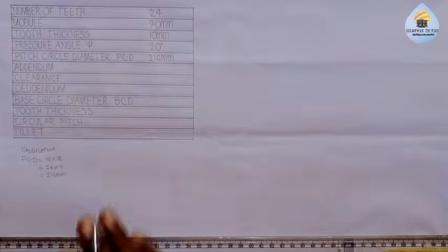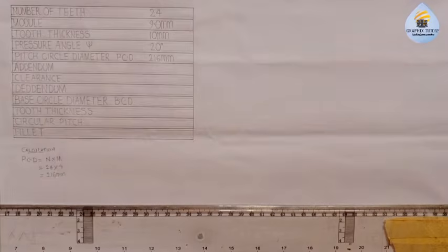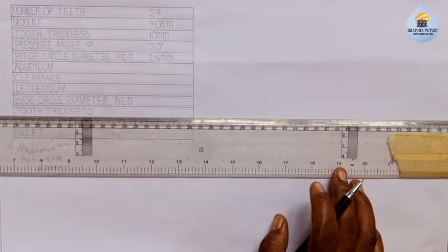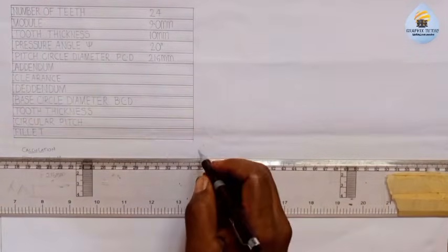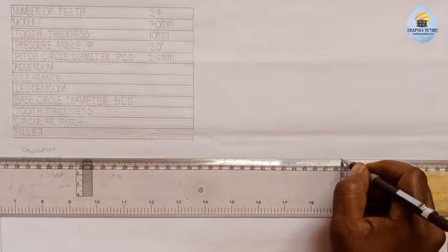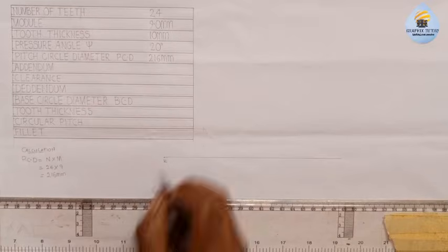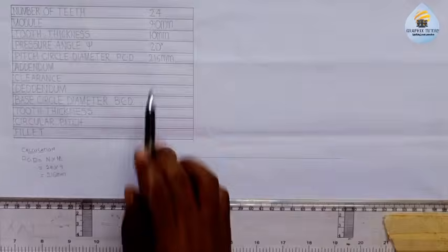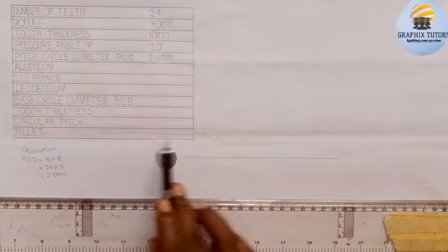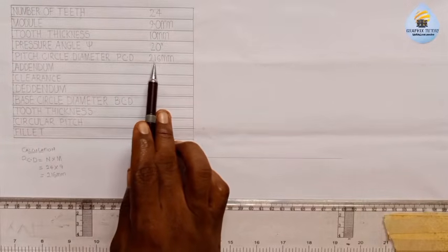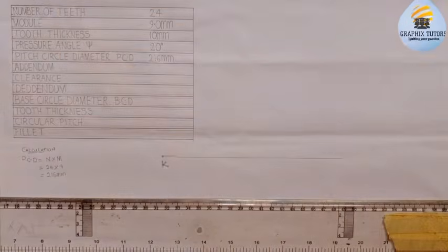You can see that? Now the next thing you do, I'll be doing them simultaneously. Then I'll pick my set square, and I'm going to draw a line this way. You can see that. I'll pick a point from here. Let me call that point K. Is that taken? Then after doing that, I'll now measure the half, because for you to draw a circle, you need a radius, and we have a diameter. So to get the radius, you need to divide this by 2. And when you divide 216 by 2, that will be 108, right?